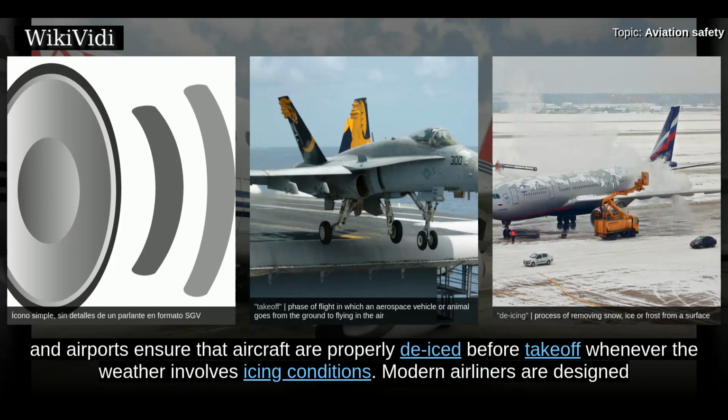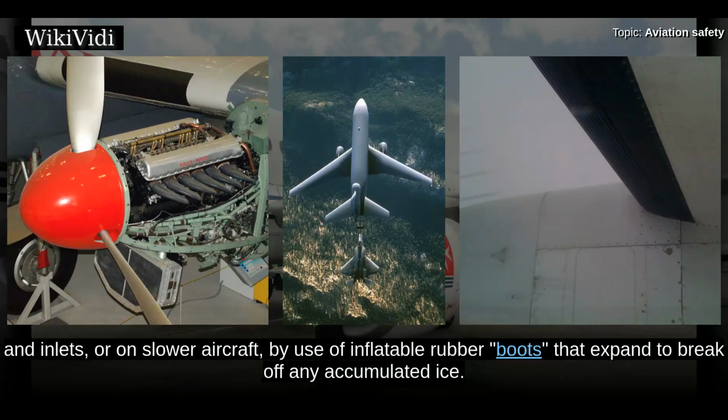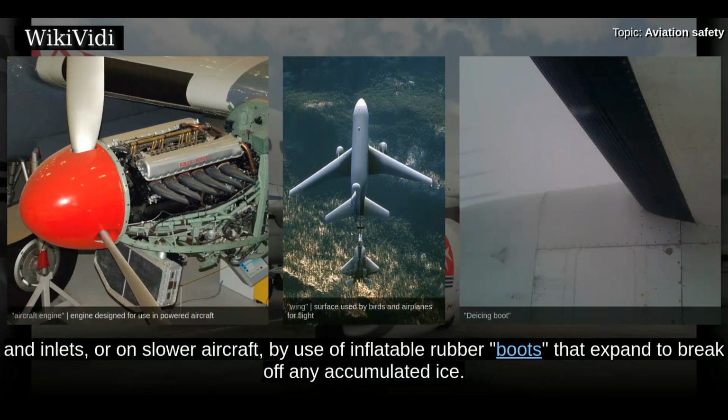Modern airliners are designed to prevent ice buildup on wings, engines, and tails by either routing heated air from jet engines through the leading edges of the wing and inlets, or on slower aircraft, by use of inflatable rubber boots that expand to break off any accumulated ice.